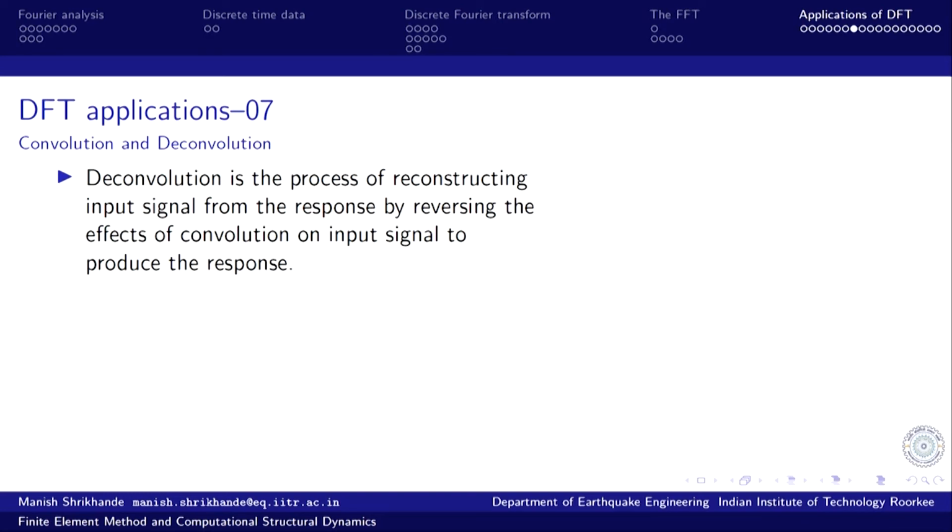So, computing the response. Now, we come to the other aspect, the deconvolution. Deconvolution is the process of reconstructing the input signal from the response by reversing the effect of convolution on the input signal. Again, if we do the time domain analysis, it is almost impossible to deconvolute anything, but in the frequency domain, because it is only term by term multiplication, deconvolution can be performed very easily.